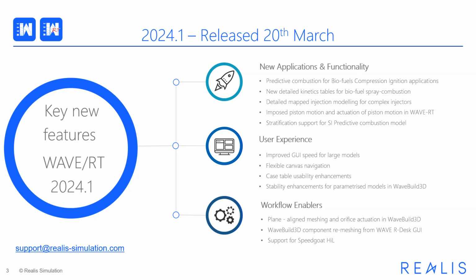We have made it easier also to work with large simulation case sets with a number of case table enhancements. We have also enhanced substantially the stability of working with parameterized geometrical models in the WAVE-Build 3D preprocessor. Focusing on simplifying and accelerating workflows, we have introduced new features which improve meshing and component preparation in WAVE-Build 3D. Also, it's now possible to remesh WAVE-Build 3D components directly from WAVE-RT's GUI.